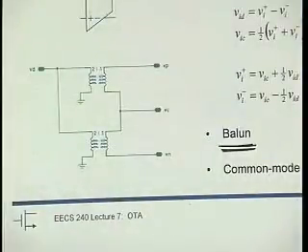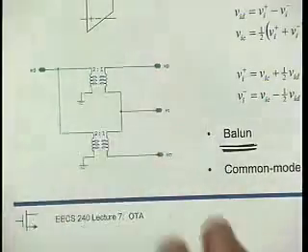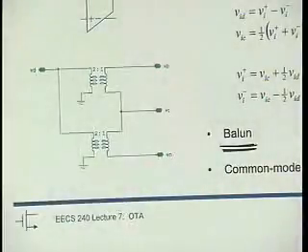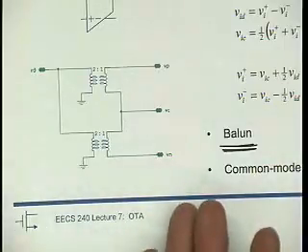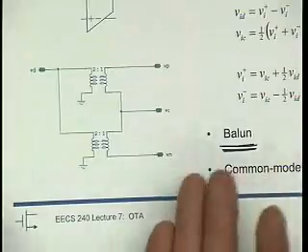And in practice, of course, building a balun is kind of a pain in the neck, because how do you get these transformers, and the transformers are not going to work at low frequency, and so on, right? Not ideal. But heck, this is only for SPICE again. In SPICE, we have perfect transformers, and they work all the way down to DC, and they're perfectly linear, and so on. So hey, why not make our life easy? If we are investigating a circuit with SPICE, use it, right?